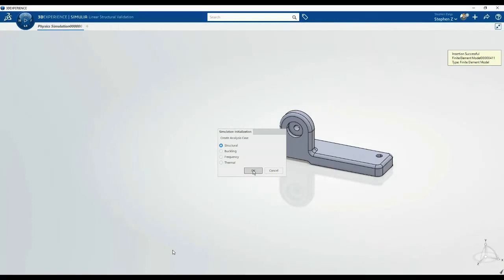We can kind of upgrade those simulations as we go and start adding things to them, right? We can add things like explicit dynamic steps where we have like an impact test or a drop test. Maybe we have more exotic material models like a nonlinear material or a hyperelastic material, or we're doing a really high impact, short time, high energy event where we might need to utilize the explicit solver. We can kind of set things up in the lower base level, the structural designer role, and then import them and kind of upgrade them as we go.